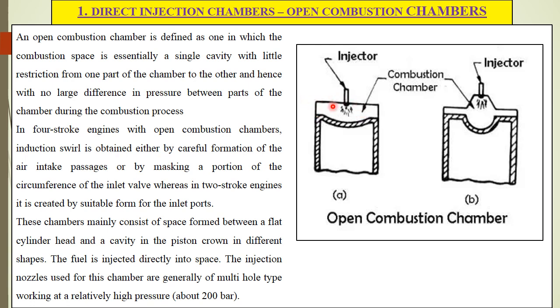Surface to volume ratio is lower, that's why efficiency is more and the heat loss is also less. No cold starting problems, as heat loss is less, meaning there is no problem that arises due to cold starting. Then fine atomization because of multi-hole nozzles, as the injector used is a multi-hole one, which injects the fuel at relatively high pressure, around 200 bar. That's why in this case the atomization is very good, fine atomization is possible.